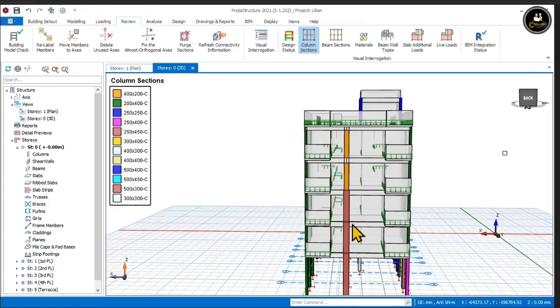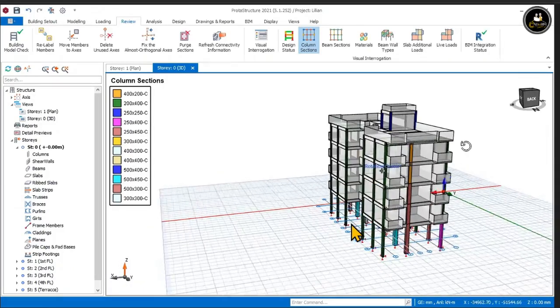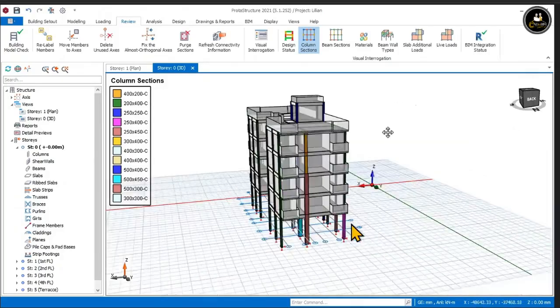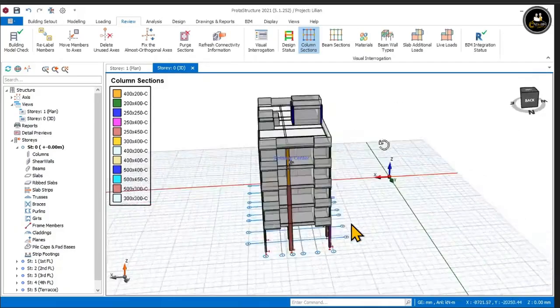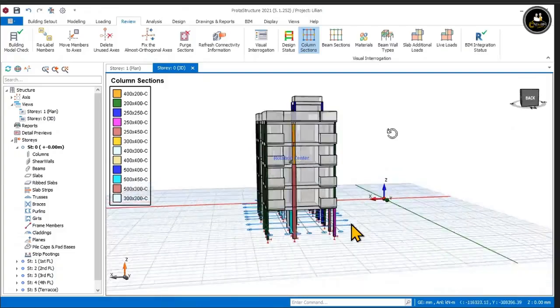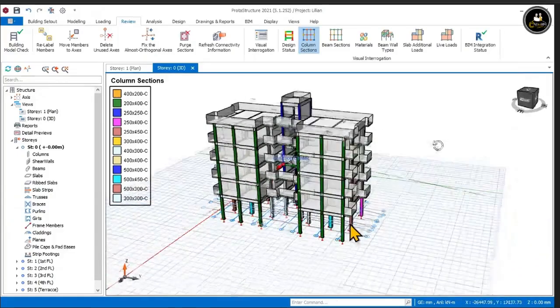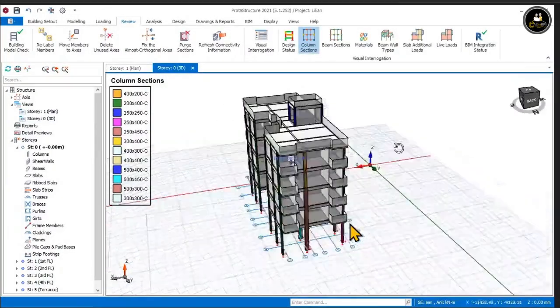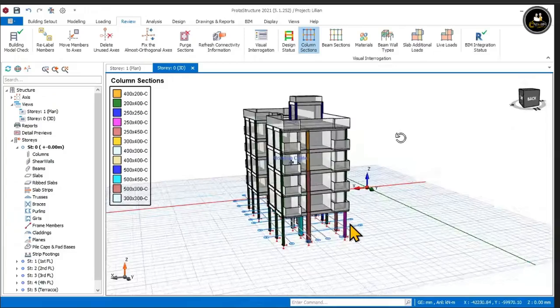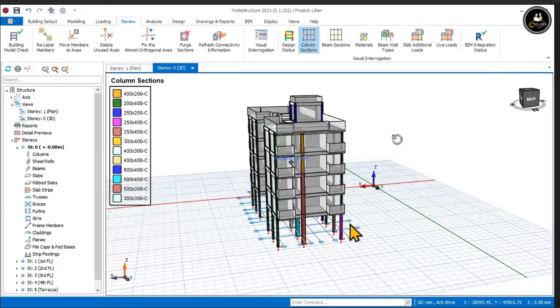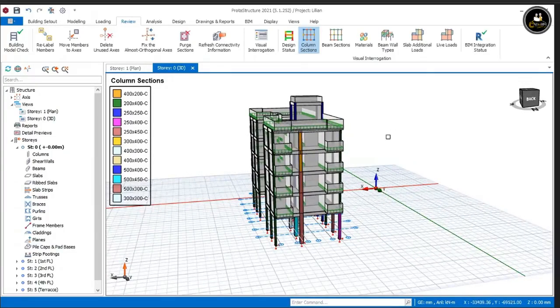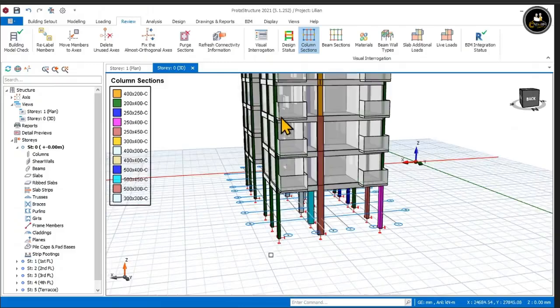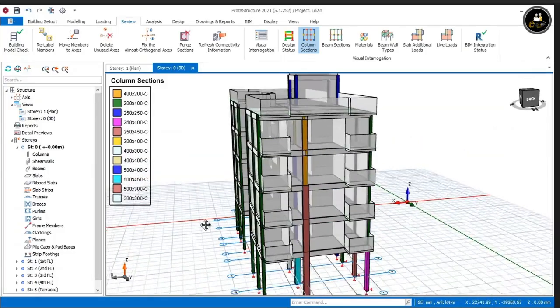And then maybe what I'll recommend, because such models are not usually very big, is that we can just opt to change the reinforcement. So instead of maybe using 6D16, you can just maintain the size but reduce the number of reinforcements so that it's easier for the fundis to construct on site. We also want to meet the verticality, the alignment and verticalness of the building.